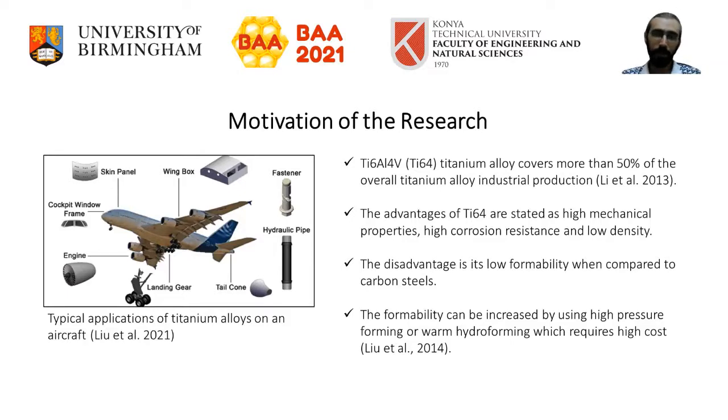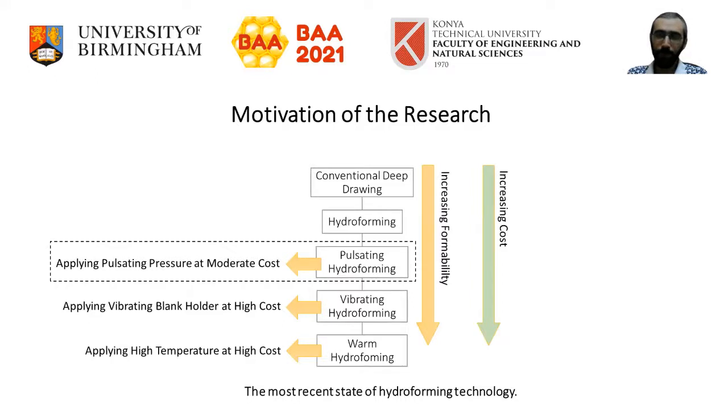Therefore, the formability can be increased by using high pressure forming or warm hydroforming, which requires high cost. So we choose to increase the formability of the titanium alloy by using hydroforming, which our team has specialized in over the last decade. As you can see, there are conventional deep drawing methods for sheet parts and hydroforming for sheet parts. And there are also advanced methods of hydroforming like pulsating, vibrating, and warm